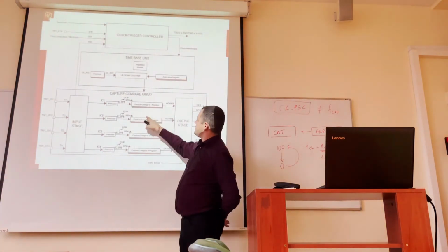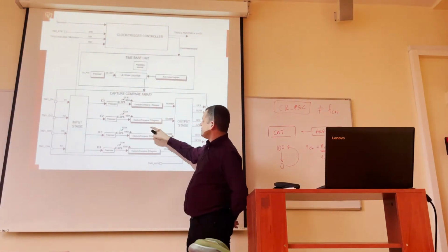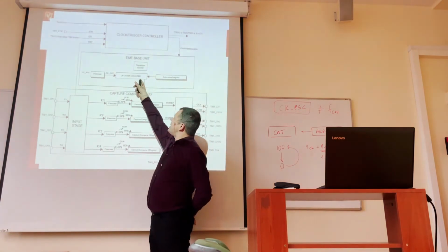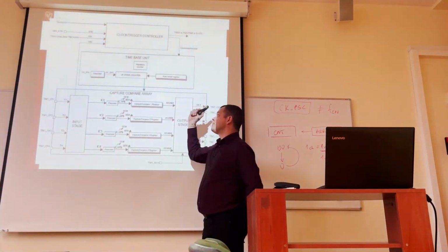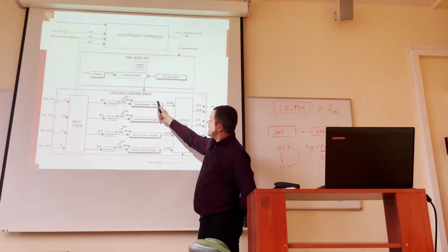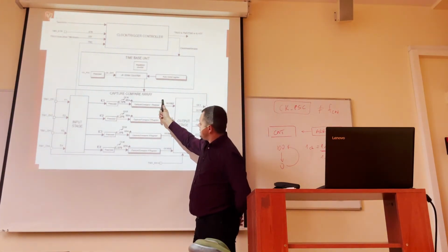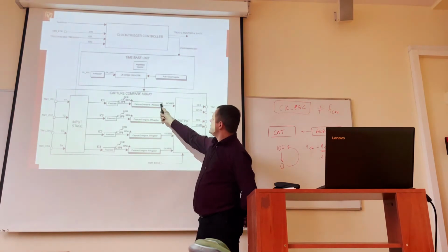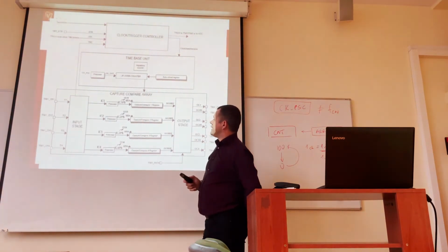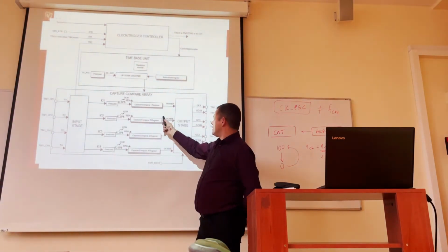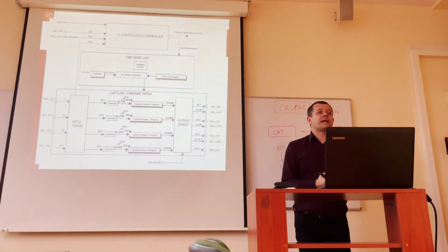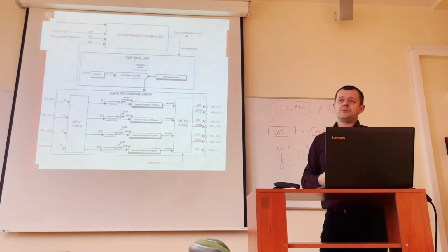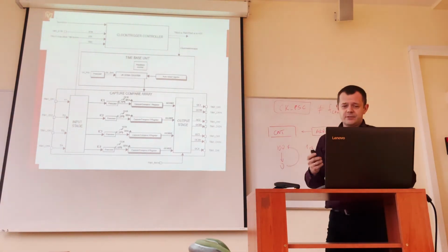In the compare registers we can put some values, and if the timer counter, the main counting register, CNT usually, reaches this value, then an interrupt is generated.